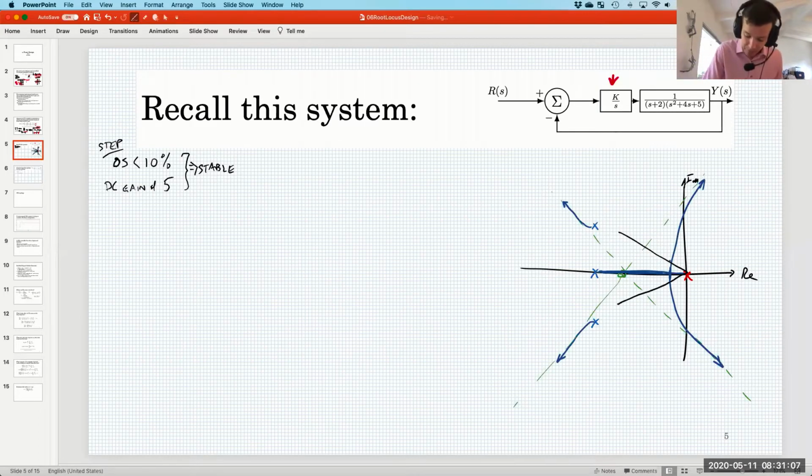So then we've got these spots that open up. If the system were second order, it looks like it's going to be fourth order. But maybe we can make an argument that if we put the slow poles here, then the fast poles can be neglected. I think that we might be able to make that kind of argument.